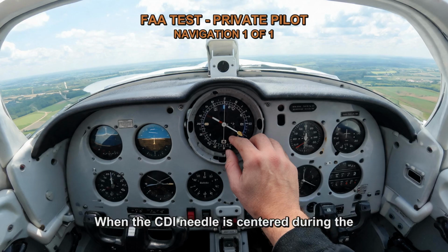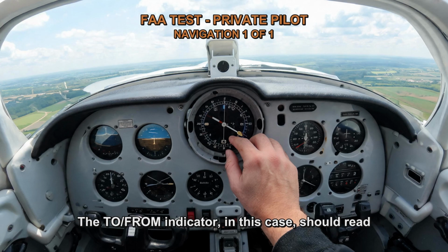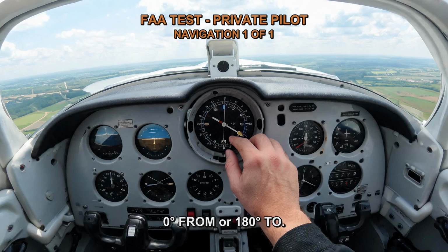When the CDI needle is centered during the VOT check, it indicates that the receiver is properly aligned with the VOT signal. The OBS should be set to the radial that corresponds to the VOT signal, which is typically 0 degrees. The TO/FROM indicator, in this case, should read 0 degrees FROM or 180 degrees TO.